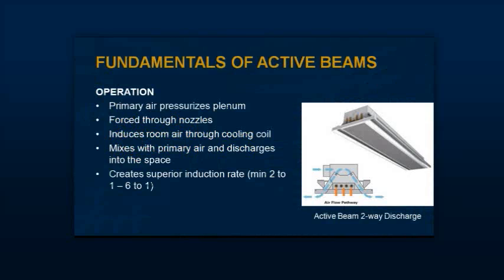It's when we start getting these radical asymmetries that we start having issues. A common one is the western side of a building in the afternoon. If you're in full sunlight, the temperature of the space could actually be ideal, 75 say, but the occupant might perceive it to be 90, and something that will generate thermal complaints. So this is something that I try to discuss with a lot of designers in an effort to understand and